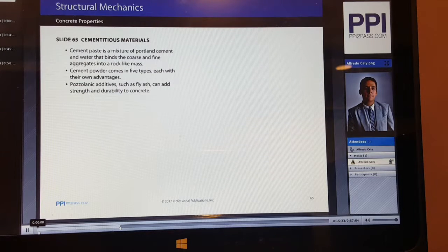Cement has a specific weight of approximately 195 pounds mass per cubic feet. Note how cement's specific weight is higher than that of typical soils, which is 120 pounds mass per cubic feet. Cement is packaged in standard sacks or bags, which weigh about 94 pounds mass or 40 kilograms.